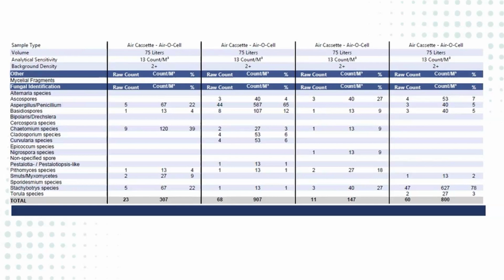The other thing that we look at commonly is we're going to collect those indoor samples and those outdoor samples. And we're looking to make sure that we don't have species indoors that don't occur outdoors, because normally, simplified version of how indoor ventilation works, we have air outside and it gets brought inside through a filtration system. So if we have a species outside and it comes inside, then we would expect that there could be some, but there should be less of it. However, if we have a species inside and it doesn't exist outside, then it must be growing somewhere inside our facility. So that's another thing we look at.